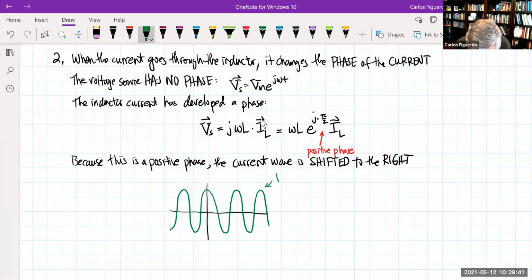So this is the voltage of the inductor, which is of course the voltage of the source. When I draw my current, note that the current is out of phase by pi over 2. If I call this 0 and this is 180, or I could just say 2 pi, then I need to be right smack in the middle of this. This is pi right here, so pi over 2 is over here. That means the peak of the current starts right here.